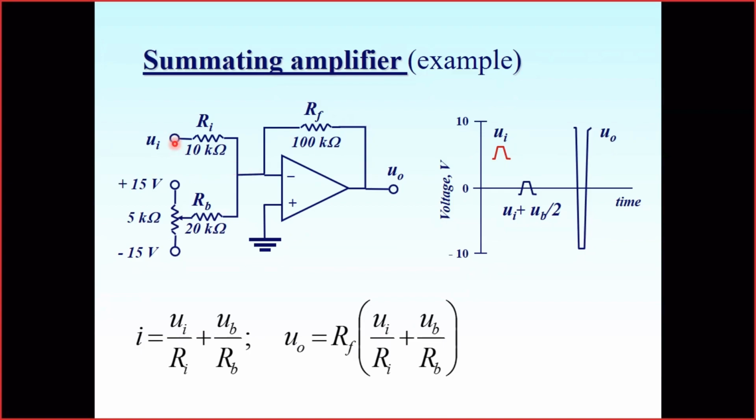I put my useful signal here, and here I may regulate the voltage at this point myself. By moving the slider of the potentiometer, which is connected between the positive and negative poles, I may change the voltage on this input. Due to this, I introduce some input voltage that will be extracted or subtracted from the total voltage.